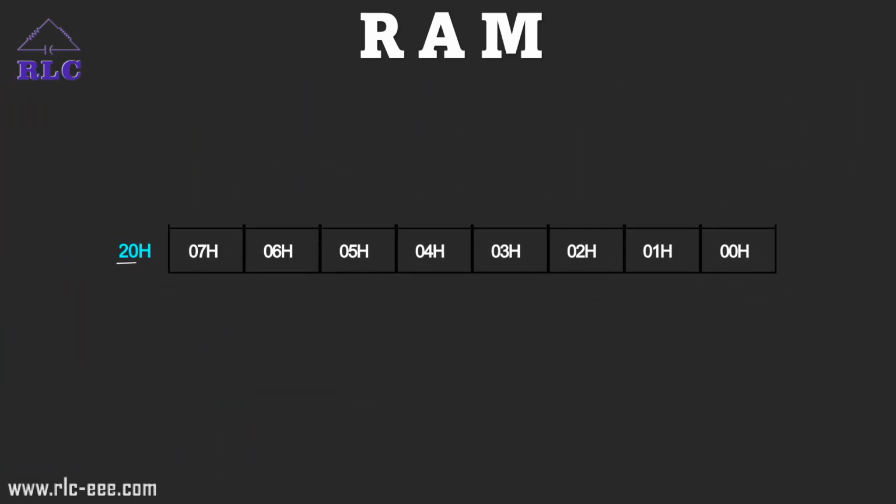Now we'll consider the 20H memory location to understand the bit addressable area. It is not necessary that the information stored should always be in the form of bytes. We know each memory location can store 8 bits, that is 1 byte.